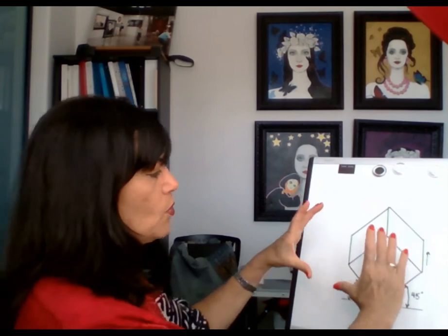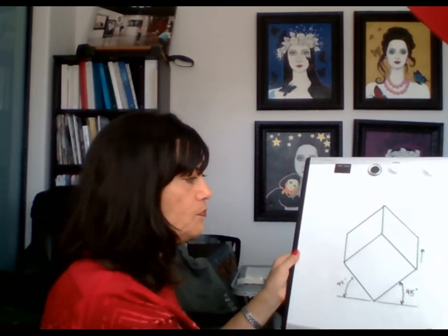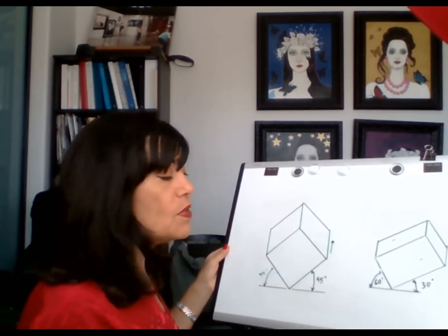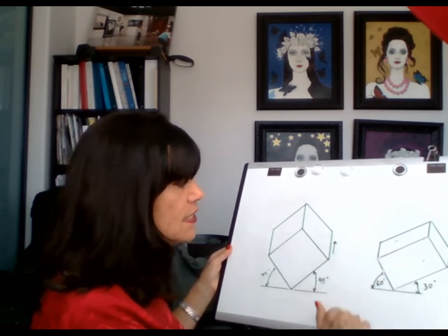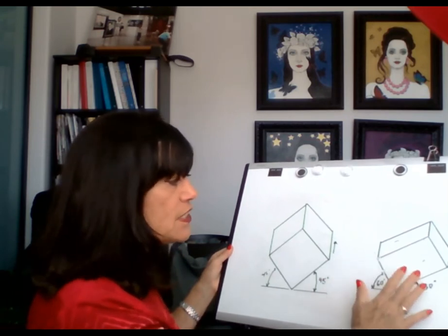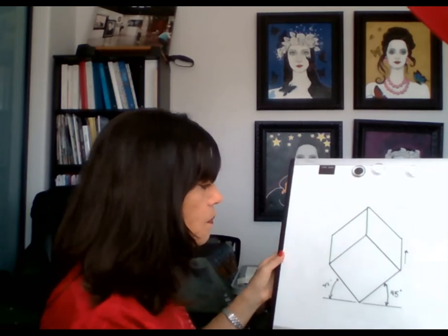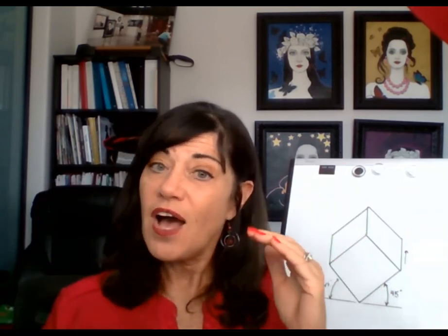Now this is a little bit more the exact object, and we project those lines. Now on this one right here, it's just a little different angle. So another way to do that is using a triangle. It's your 30-60, and you're just tilting it a little different. It's no different, it's just a different angle shift, that's all. So that's one way to do our oblique axonometrics. And just a real quick idea of just showing how you project. And once you have the height, you can connect the dots and create a three-dimensional wonder.